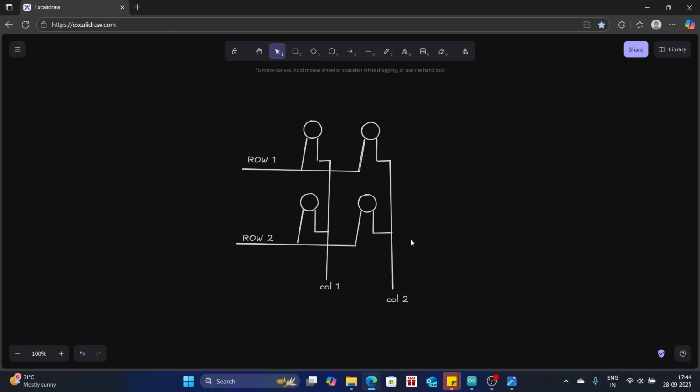In general, this happens so fast, the LEDs are getting turned on and off so fast, that the eye thinks that both of these LEDs are switched on. This effect is called persistence of vision. In reality, the LEDs are getting switched on and off in an interval of milliseconds, which our eyes cannot catch. So for the naked eye, it feels like both LEDs are switched on. That's how we control LEDs. If we want to control a different set of LEDs, that's how we do it.